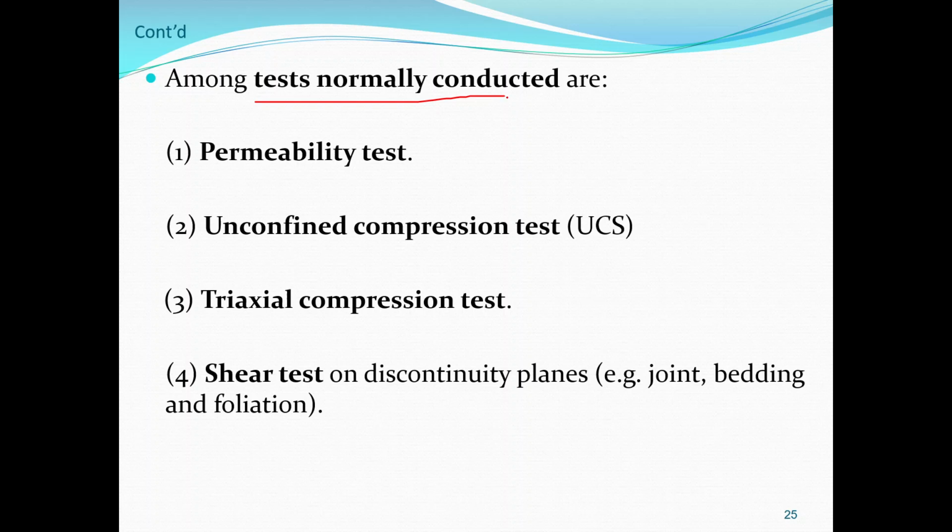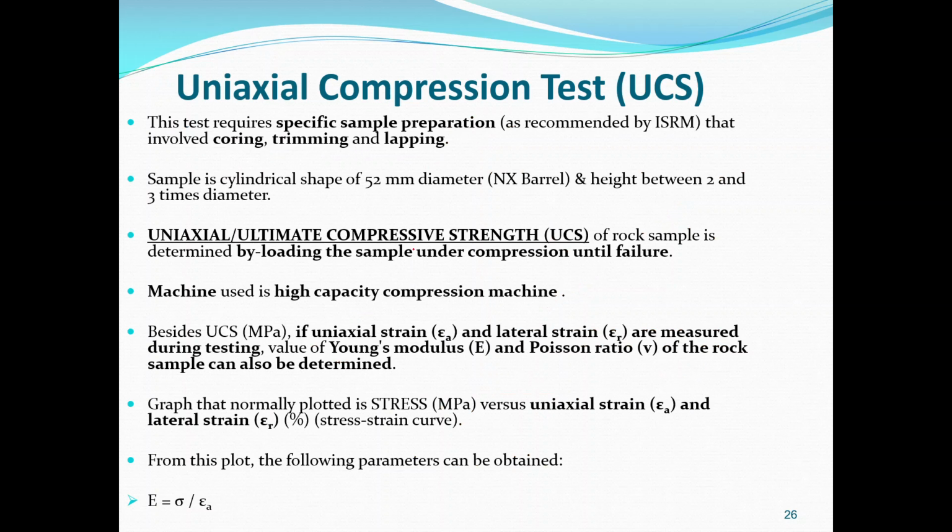Among the tests that are conducted are the permeability test, the unconfined compressive test, the triaxial test, and the shear test. Normally the shear test is conducted on a discontinuity plane, joint or bedding, and foundation. The first test we discuss is UCS, or the Uniaxial Compression Test.